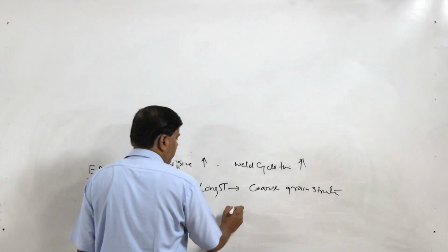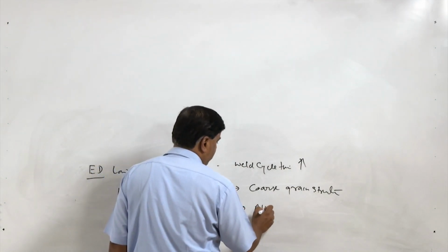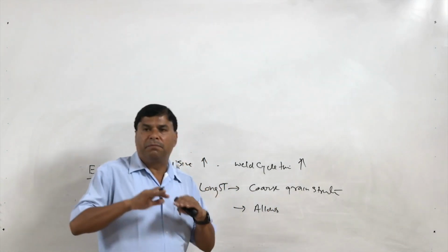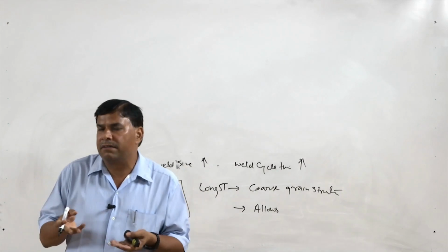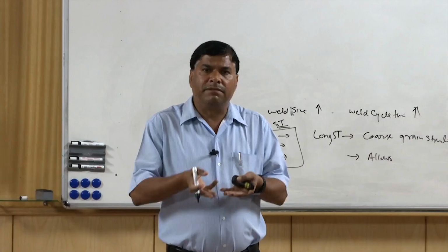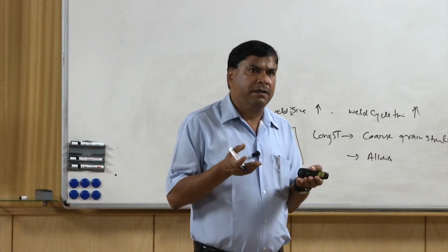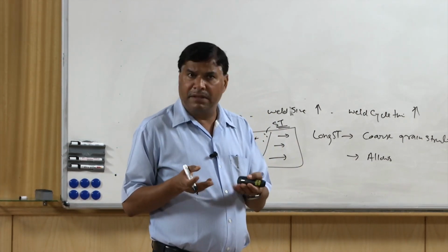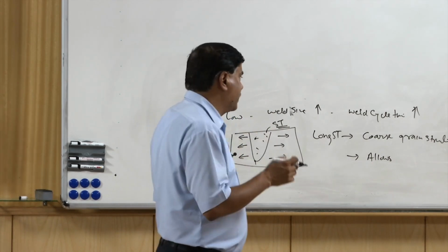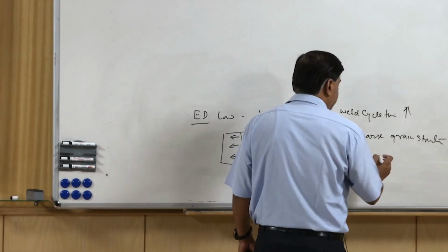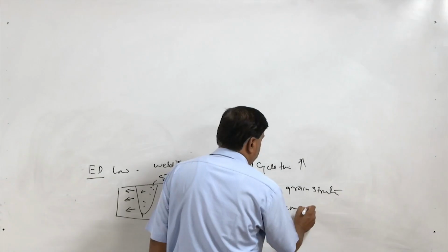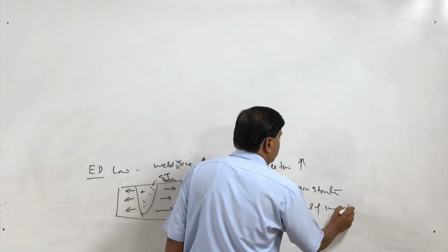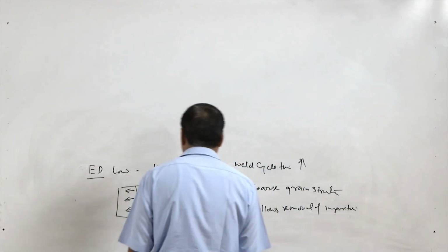At the same time, it allows the impurities to come up to the surface. Like if gases are present in the weld, then they will come up to the surface, and if inclusions are being formed, they will get enough time to float over the surface. So it allows removal of impurities in the form of gases and inclusions.